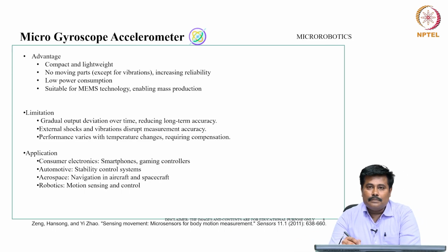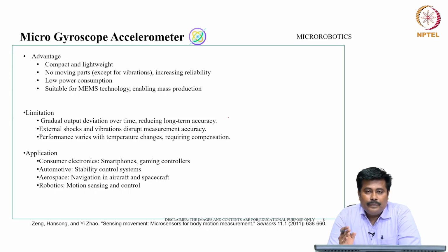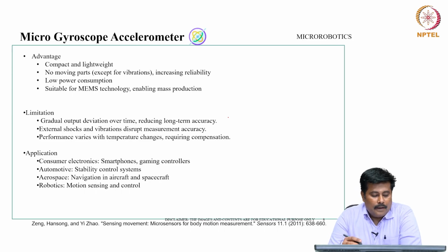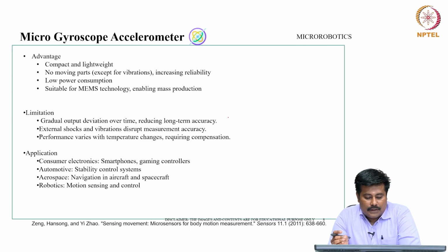From a limitation point of view, it has a gradual output deviation over time, reducing long term accuracy. External shocks and vibration disrupt measurement accuracy. Performance varies with temperature changes, requiring compensation.